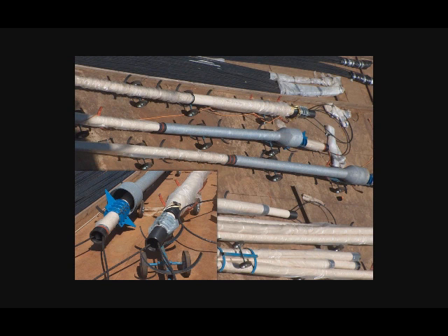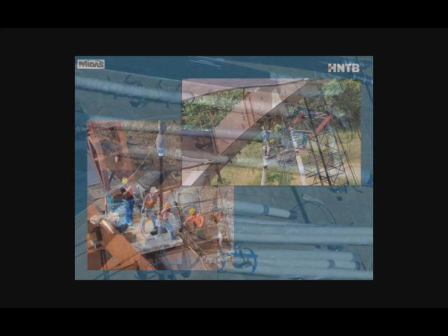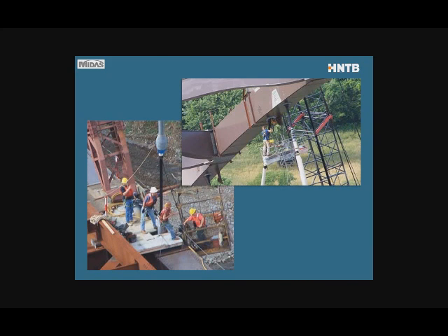Strand installation and cable installation, as I mentioned earlier, is done with very light equipment, one strand at a time. So here we are on the barge. The lower insert shows one strand is installed. That blue device is just a collar to hold up the anti-vandalism pipe. You can see in the larger picture the cable with the anti-vandalism tube, and then transitioning to the HDPE pipe. So the whole thing gets lifted in, one strand plus the HDPE pipe, and then the next step is just one strand at a time is attached to a little winch system.